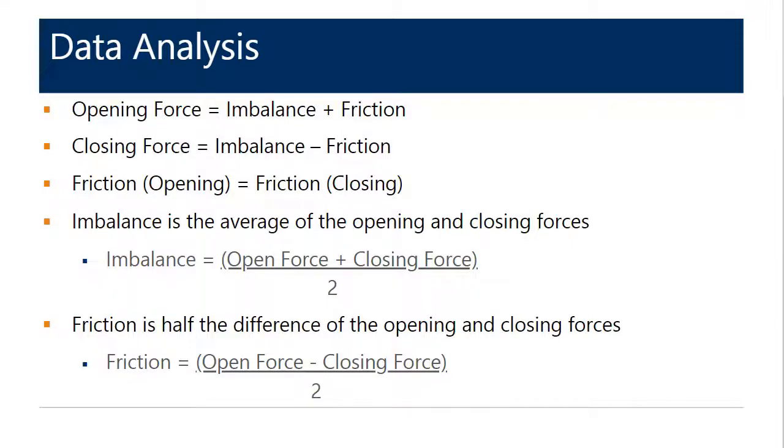Okay, next question. I've been told that my bascule bridge is light when closed but heavy when open. What can I do? That's a good question, and it gets back to our discussion of the balance parameters which control leaf imbalance. We can show those, the W, R, and C there. I think it's this one.